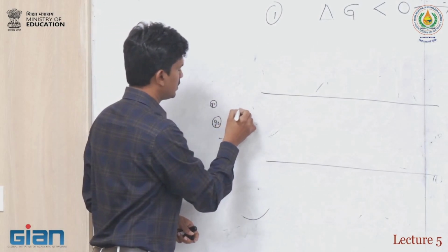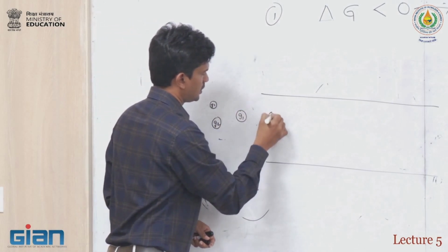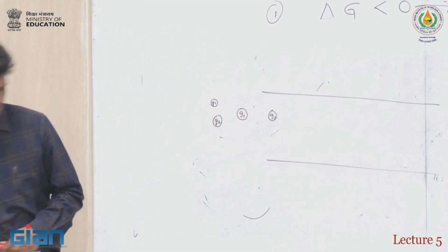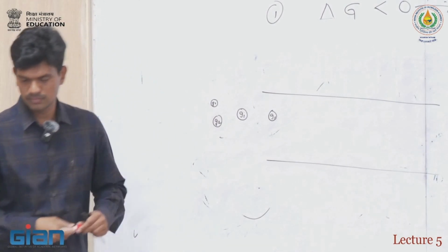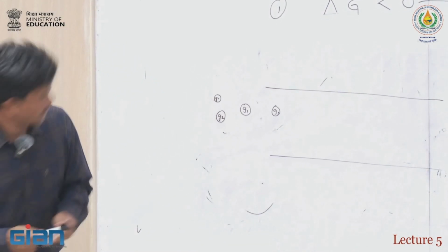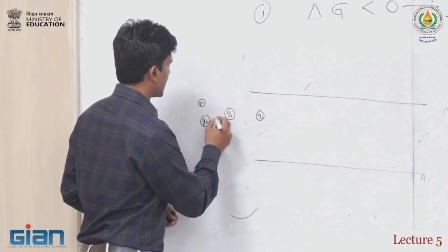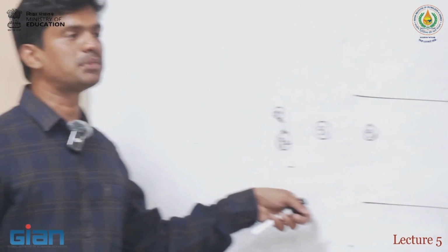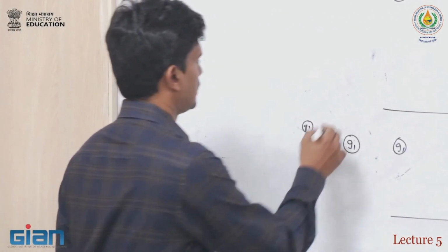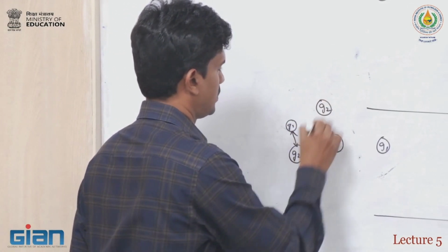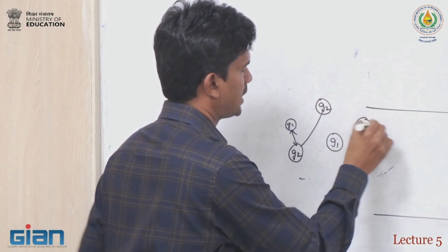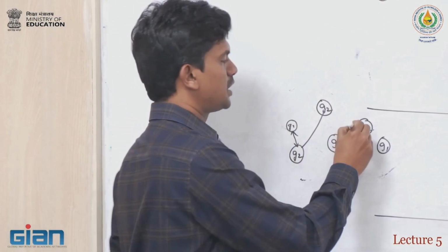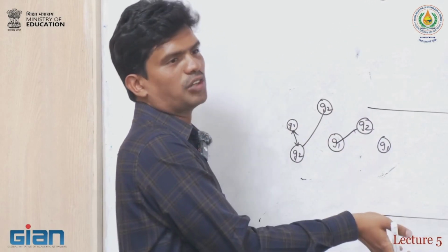So then, you have G1, you have G2. I wish we had one more color. All are black only. Okay. So the continuum diffusion is characterized by the collision between gases of different types, not of the same type. This usually happens at higher loadings because at higher loadings we have more gas molecules, so they try to collide with each other rather than colliding with the walls.